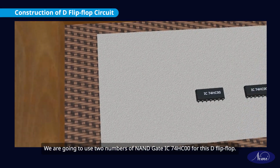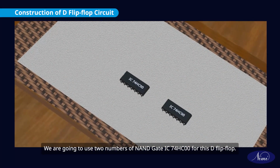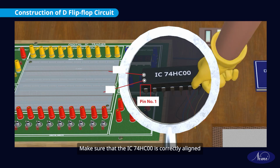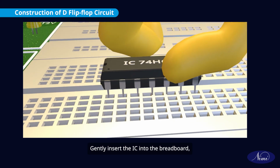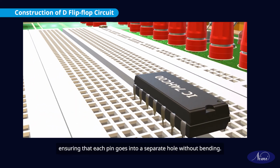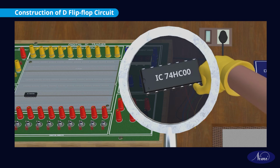Construction of D flip-flop circuit and verification of the truth table. We are going to use two numbers of NAND gate IC74HC00 for this D flip-flop. Make sure that the IC74HC00 is correctly aligned and that pin number 1 is in the right position. Gently insert the IC into the breadboard, ensuring that each pin goes into a separate hole without bending.